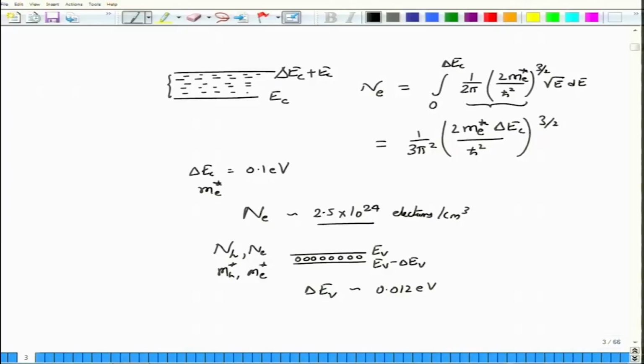So, you normally dope your semiconductor laser diodes with larger values of N doping compared to the values of P doping. So, what we see is that for the same charges, the same concentration, delta EV is smaller compared to delta EC.